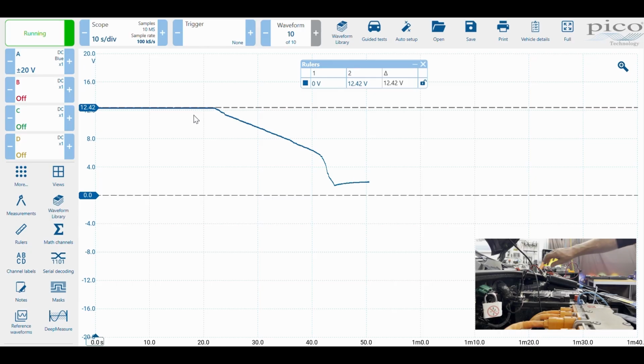So we can short that out. So again, cross negative, remember, via a fused lead, and that shorts it straight to ground, as you'd expect, or certainly 0 potential between leads. Disconnect, and just note what happens now. That capacitance is still there. There is still residual in this vehicle.